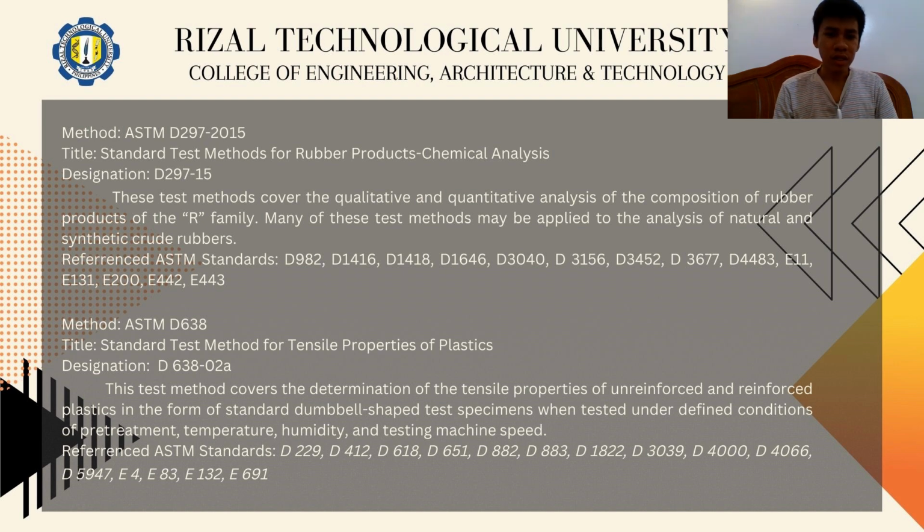Next, ASTM D638, Standard Test Method for Tensile Properties of Plastics. This test method covers the determination of the tensile properties of unreinforced and reinforced plastics in the form of standard dumbbell-shaped test specimens when tested under defined conditions of pretreatment, temperature, humidity, and testing machine speed.